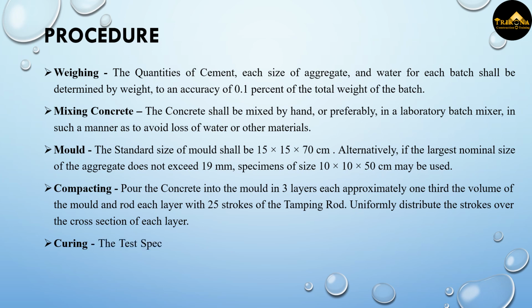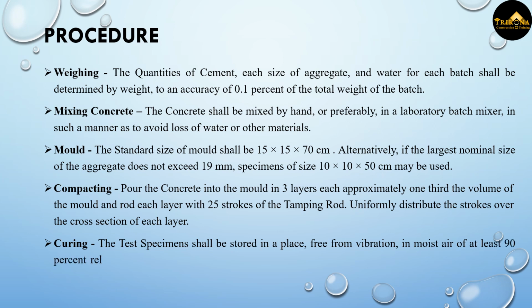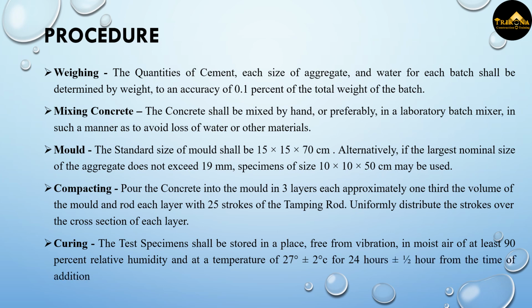Curing: the test specimens shall be stored in a place free from vibration, in moist air of at least 90% relative humidity and at a temperature of 27 degrees plus or minus 2 degrees Celsius for 24 hours plus or minus 1/2 hour from the time of addition of water to the dry ingredients, and then place the specimens in a water tank for 7 and 28 days.